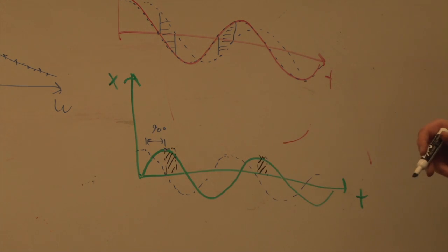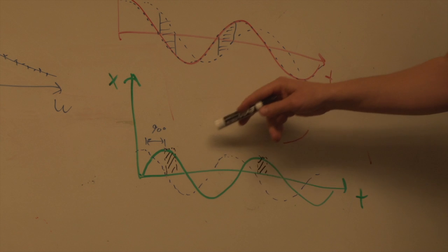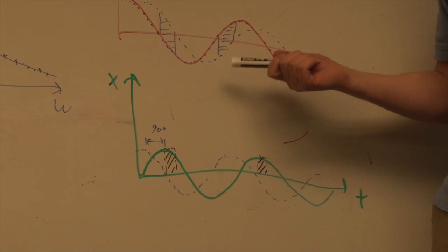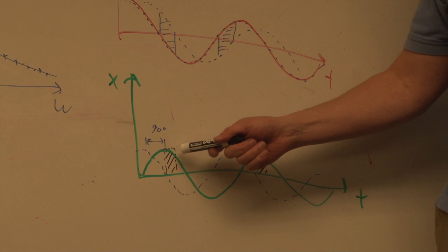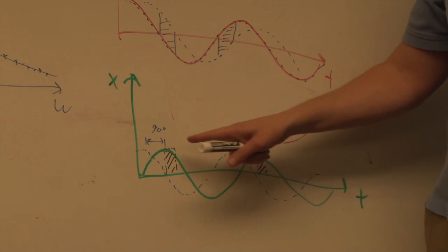Basically, the only rule that you have to follow is that you only push in the direction that it's moving. As long as that's obeyed, you're always doing positive work. It will find that resonant curve and then just ride that resonant curve out. But your efficiency is going to depend on your actuation system. So if you can produce high forces at low speed, like a human's arms, you want to drive there.